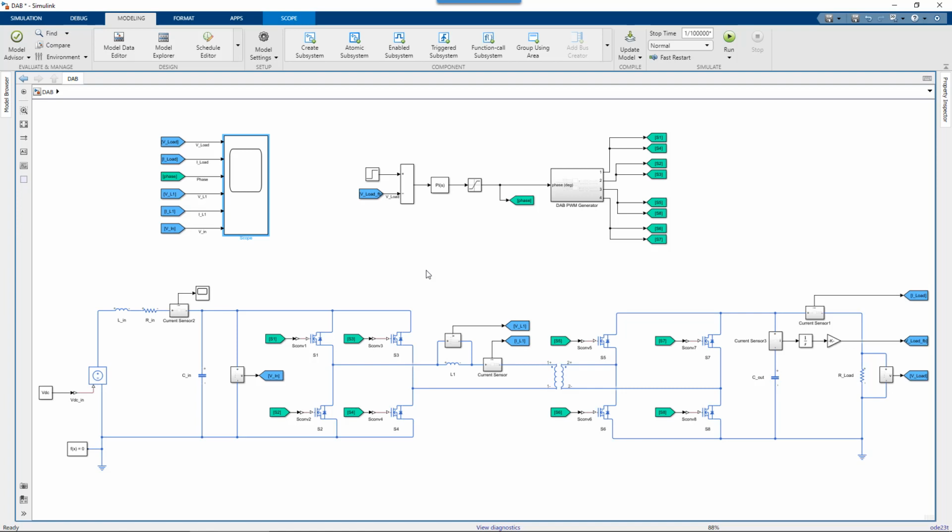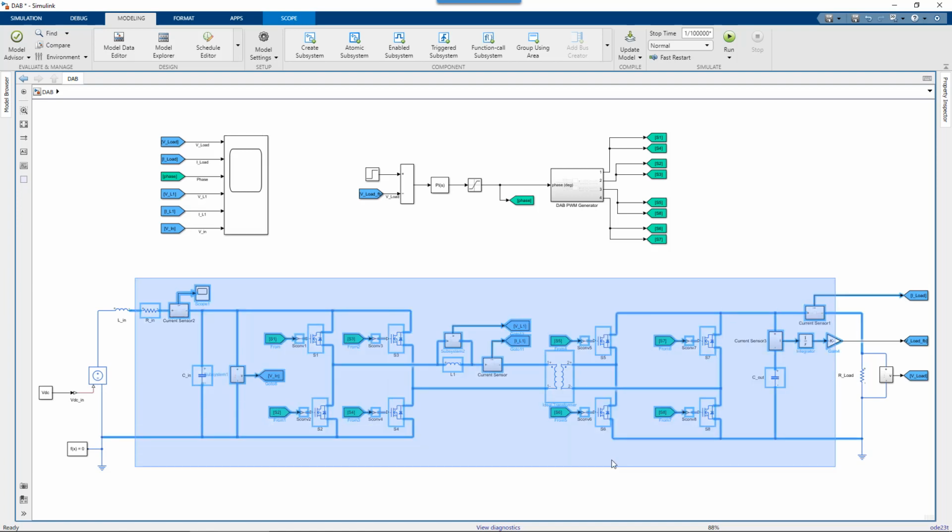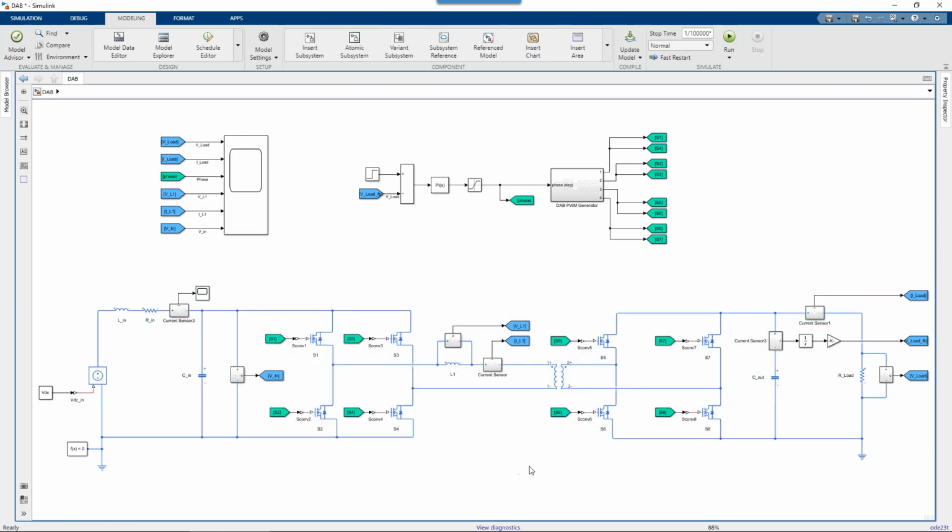If you do those, still nothing changes, you should actually really consider, do you have a realistic model? This model here is completely based off an actual hardware design, so my parameters come off an actual hardware design. They're not arbitrary. If you put arbitrary parameters in here, there's a high likelihood your simulation is going to perform badly because you're going to have unrealistic circuits, and the time constants of them will then actually cause problems for the solver, whereas if you put in what's a good design, it will often actually simulate quite well. So those are some of the rules of thumb to use when you're approaching getting your simulation working correctly.